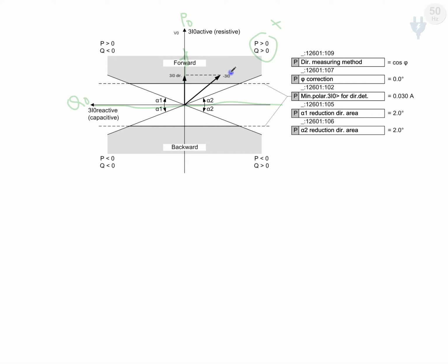Whenever this zero sequence current, here it is shown as a minus 3I0. The reason is that mostly in positive sequence current I1, for example, in our system, this I1 flows in the forward direction, in this direction. During normal operation, we call it the normal current, that is positive sequence current. But the zero sequence current flows in the reverse direction, that is I0.